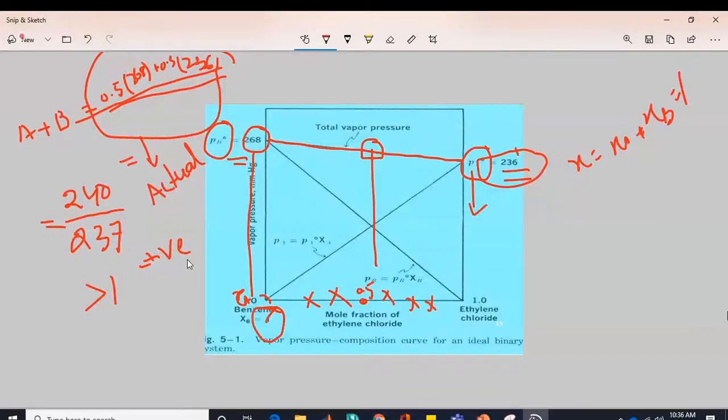Now, if you lower this pressure to 70 mmHg, then at 70 mmHg your water can boil at 40 degrees, because at 40 degrees C, the vapor pressure of that water is 70 mmHg. That's why if you equalize the atmospheric pressure to its vapor pressure, your liquid is going to boil. So this is one of the examples that helps you understand how reduced pressure or vacuum distillation works.